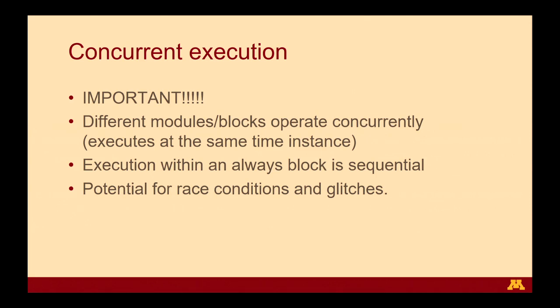unless you explicitly give some kind of control to ensure the ordering, unless you have some sort of handshake signal to tell that, okay, now this module is done, proceed to the next module. Because by default, all modules execute in parallel at the same time, and the best way to imagine this is that every single module is a parallel thread. And this is not just for modules. As we will see later on, Verilog has something called always blocks and assign statements. These blocks also behave as concurrent executions.